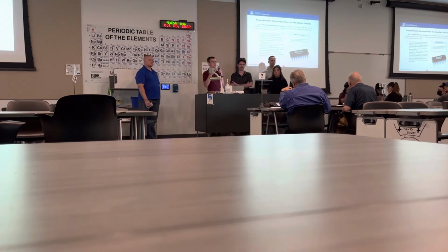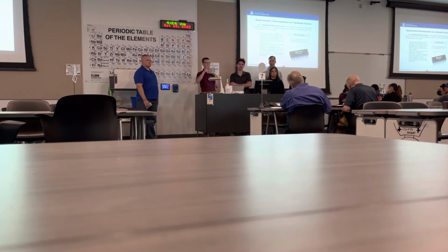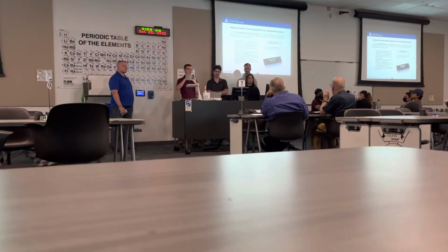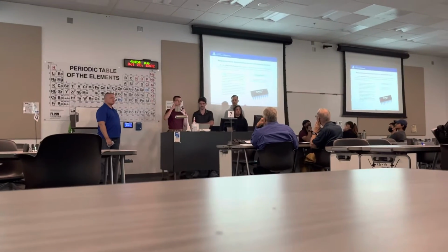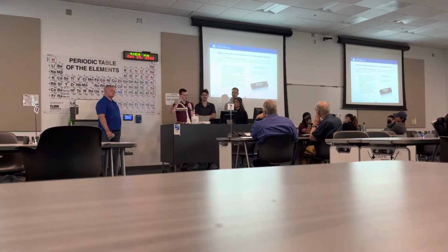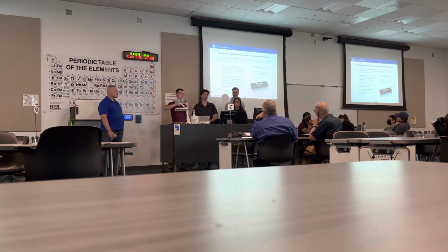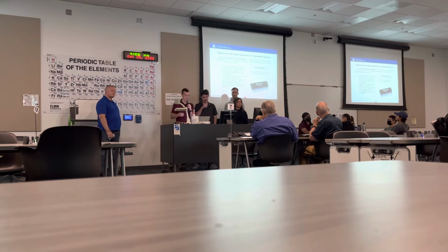First of all, one of the ones I'm most interested in is handheld device accuracy. This particular requirement is going to be verified at the system level, but it is derived to certain subsystems, for example, the ISE sensor system. This is where, as mentioned before, we have this analog to digital conversion process going on. So we're going to have to be very conscious about the values we choose for the bit resolution because, as mentioned before, high resolution is necessary to achieve the desired accuracy, but it also drives us closer to a smaller noise floor, so we might start seeing noise in our system. So this is definitely a requirement that we're going to want to dig into and start experimenting with as we do MVP1.